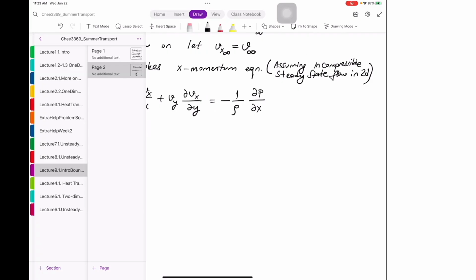If you want to include the effect of the gravity as well, there is a rho g term, or maybe when you divide by rho, you have the gh term, but you can combine it with the pressure and you can call it the modified pressure, and some of the sources use the fancy p for that. So instead of including the gravitational effects, you can actually dump all those into the p, and you can call it a new variable called fancy p. Okay.